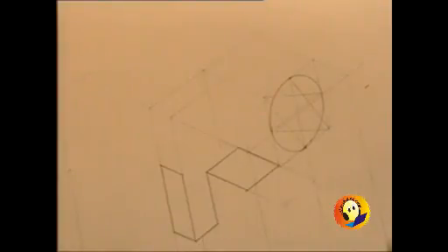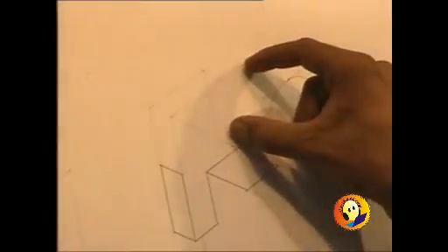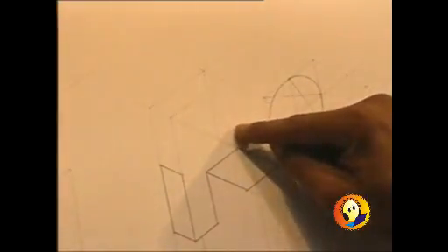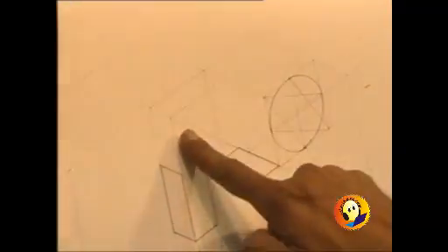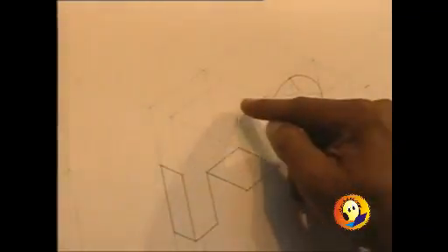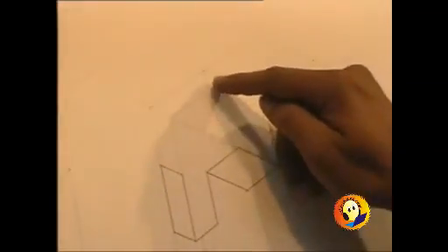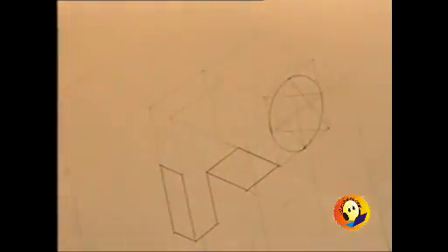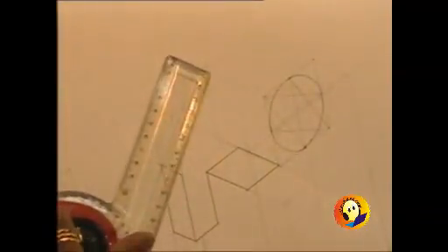Now this cylinder is going through, and we are required to draw the curve on this particular face, which is at a distance 15 millimeters, because this is a plate that is meeting the cylinder. So we require a center at a distance 30 so that this arc can be drawn, and also a center on the back because there is going to be a curved portion over here. But instead of reproducing the same construction of the rhombus, we will now prefer to only shift the centers.